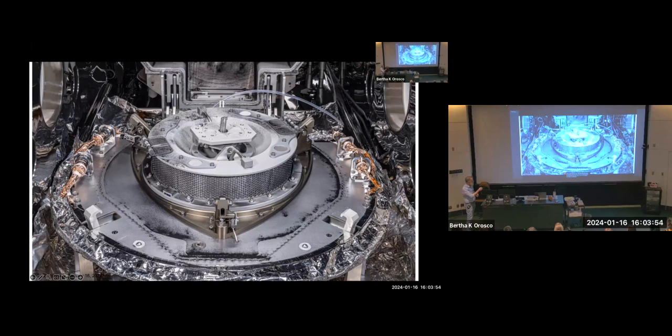The canister was opened very quickly at Johnson Space Center, revealing the TAGSAM, which is here, about 30 centimeters in diameter, if I didn't give you the scale earlier. And then right away, we saw this nice fine ring of dust, and then a second ring of what we would call intermediate particles on the order of a millimeter or so. And they have a distinctive pattern which matches the braided wire seal. So you can see here's a braided metal seal. And these intermediate particles somehow got pushed past the wall and got stuck in that braid. It's interesting to me why the fines were accumulating there and the intermediates made it farther.